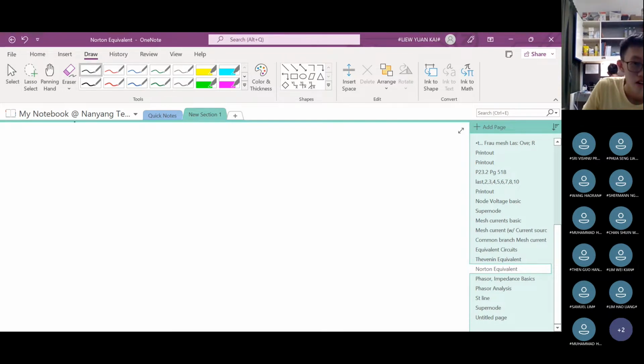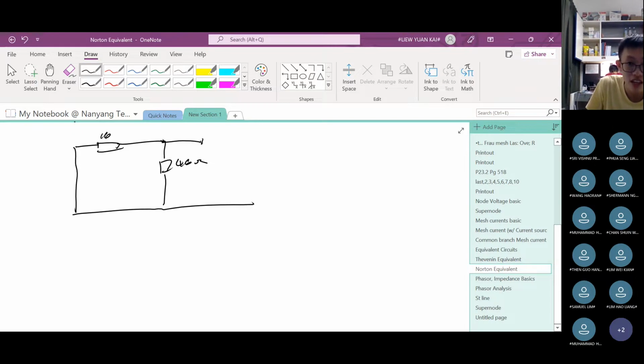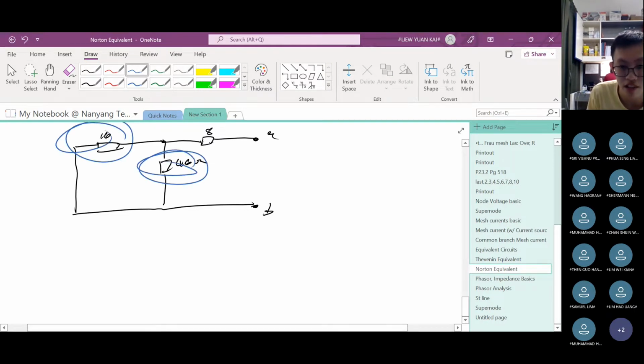Okay, remember at the very left side there was a voltage source, but now I'm going to replace it with just a piece of wire, a short circuit. And this is the 10 ohm. Everything else I just copy. This is 40 ohms, and over here this is 8 ohms. We want to find A and B. Looking through A and B, what is the total resistance of this configuration? Let's use the classic formulas that we know. So let me ask you this: 10 ohms and 40 ohms, are they in series or parallel?